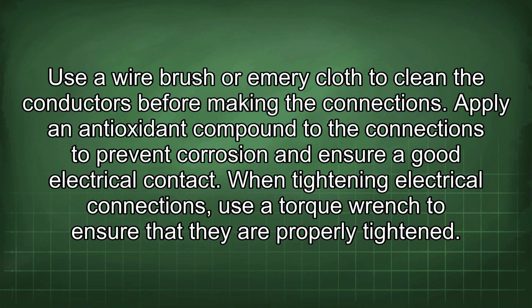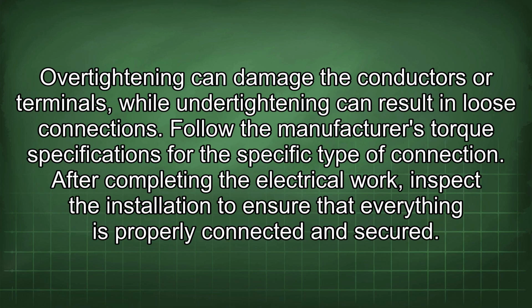When tightening electrical connections, use a torque wrench to ensure that they are properly tightened. Over-tightening can damage the conductors or terminals, while under-tightening can result in loose connections. Follow the manufacturer's torque specifications for the specific type of connection.